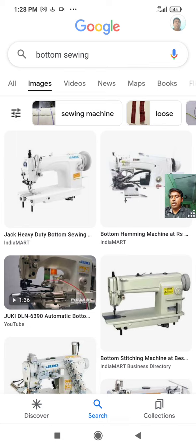So soaking the garment in a high concentration bleaching solution and subjecting it repeatedly to harsh low phosphate detergents will corrode brass chain and sliders and harden the teeth of plastic zippers. This condition has lately been accentuated by pre-washing garments in industrial laundries prior to sale. Some retail customers return garments for zipper failure in which the seams are open and the textile yarns are broken because of severe chemical degradation.